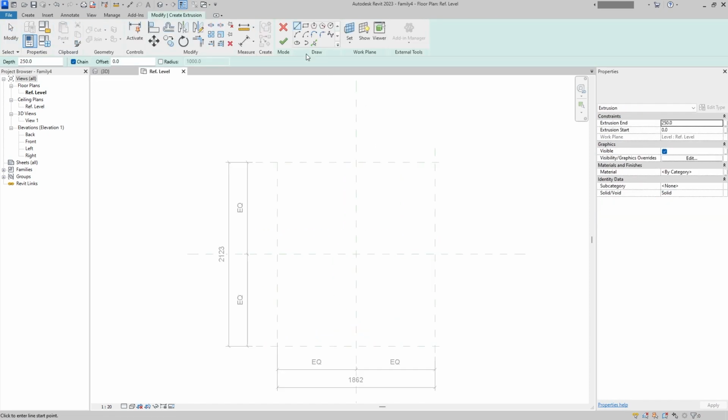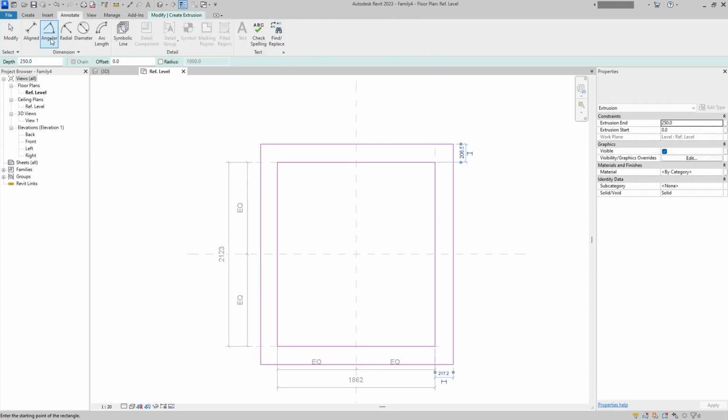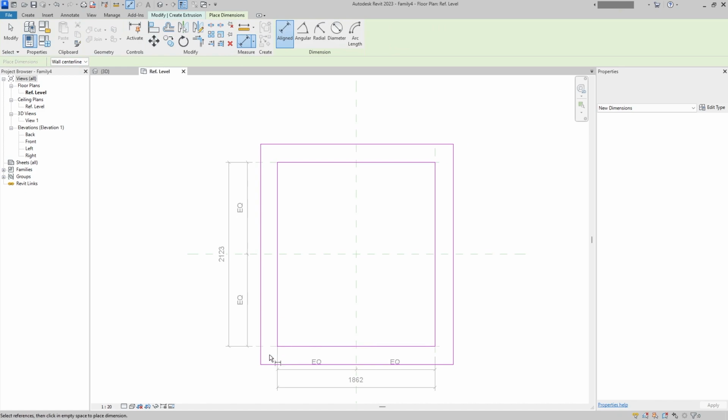It's time to add the shape of the flange. For that we will use the extrude instrument, and we will indicate the inner line that will match the reference planes and the outer line of the flange that will indicate the width of the flange itself.